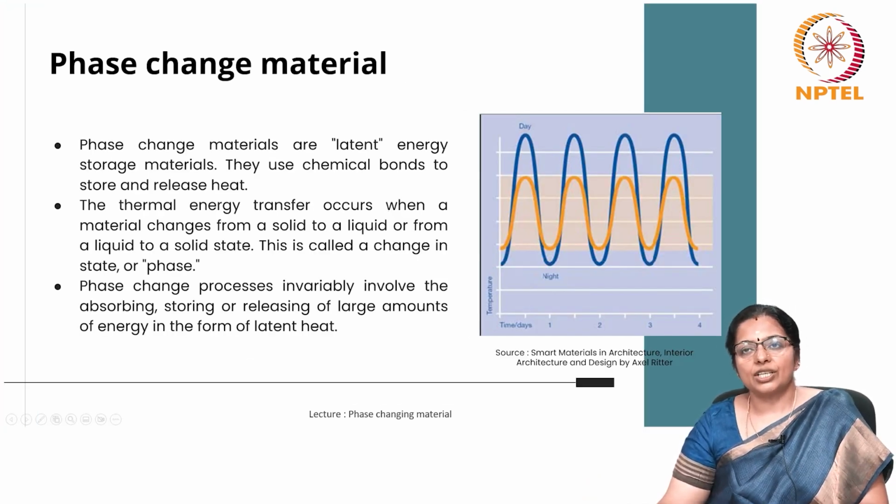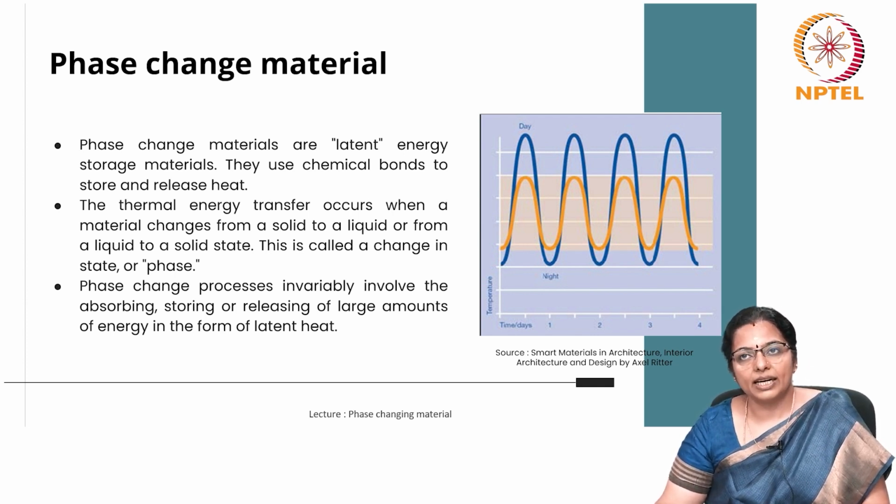So, the phase change materials or PCMs can give out latent heat at a wide range of temperatures from sub-zero to several hundred degrees. The heat on demand requirement is satisfied by phase change materials which work at specified temperatures.